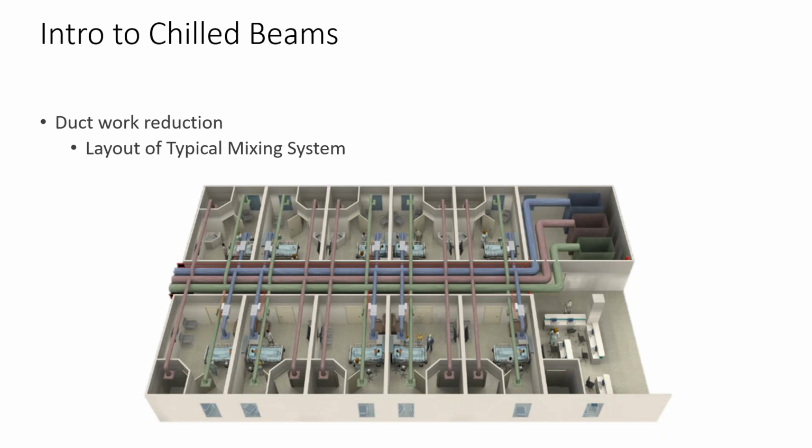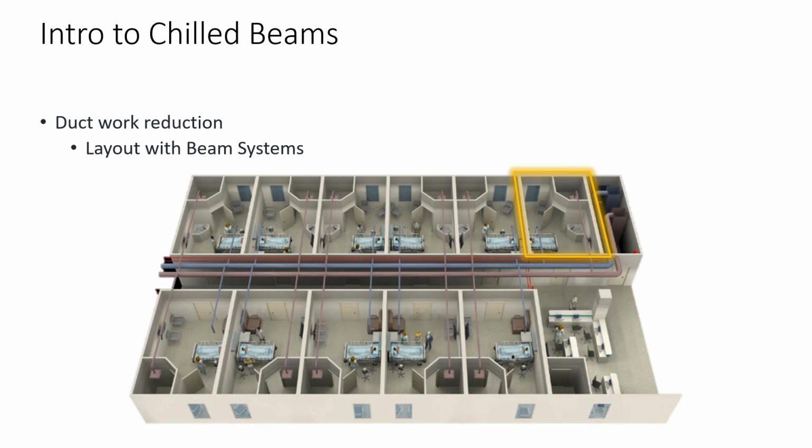But in the top right, you've got the 3 duct shafts in the room, and enough space for the duct to run out of the room through the corridor, the ceiling space. Now, when we shifted over to a chilled beam approach, they were actually able to convert that space, shrinking it down enough to add in a whole other patient room bed into that floor. And so this was a multi-story building.